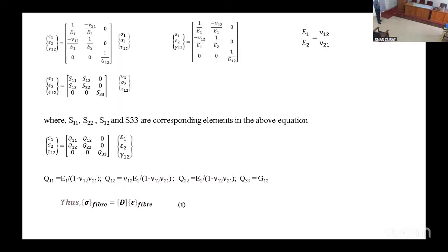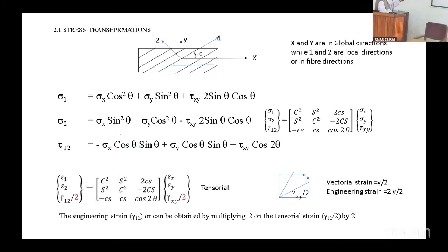So this we have decided. In the isotropic material, property is represented as the D matrix. In the case of composite, initially from the known place we have to go to the unknown place. Initially, the D only we put. Later, in the next slide we change it, because in composite D represents bending rigidity. Therefore we put Q instead. Okay, this we talked about. We will have it this way.